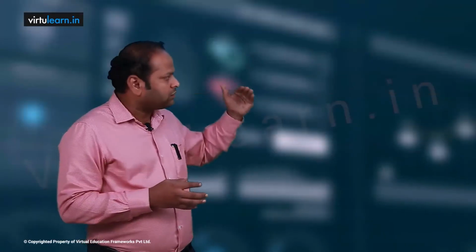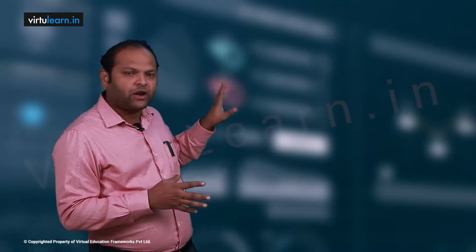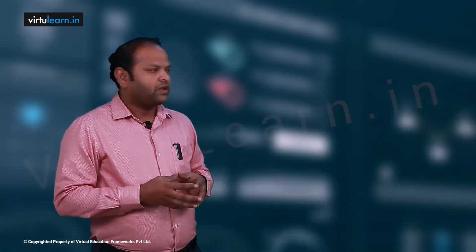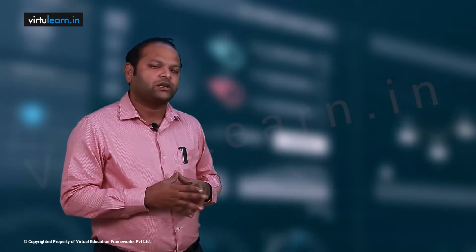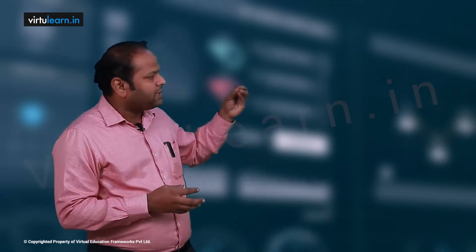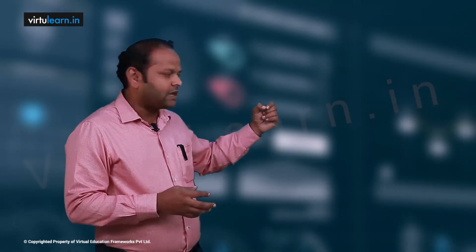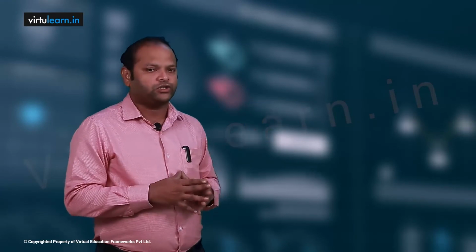Now what is path 2? In the Nyquist path, path 2 is defined as r e power j theta, where the radius tends to infinity and the angle is of course plus 90 to minus 90. When you map that into the GH plane, it is going to be one semicircle or more semicircles with radius r tends to 0. Therefore, we can simply ignore it, or it can be taken as a single dot at the origin. So I can take that dot. This is path 2. Now coming to path 3.